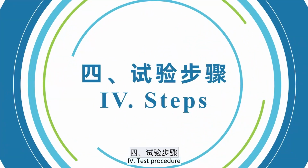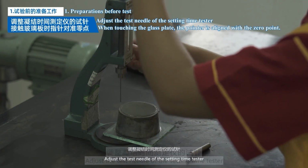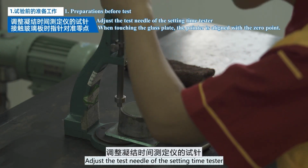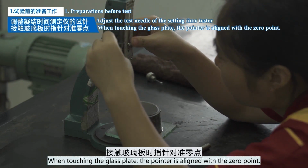4. Test procedure. 1. Preparations before test. Adjust the test needle of the setting time tester. When it touches the glass plate, the pointer should be aligned with the 0 point.